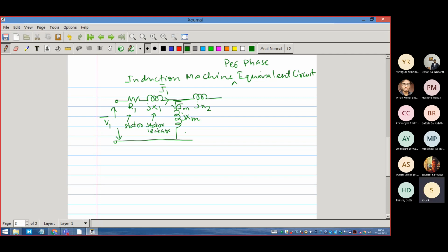So that is the flux level of the machine, and in the previous class also we talked about that we must maintain it constant in order to maintain the machine at the maximum possible flux level without saturation. So our intention is not to saturate the machine, but to extract maximum torque out of the machine at the minimum current. We must also try to place the flux at the maximum possible level. Okay, so that's why a new conceptual current has come.